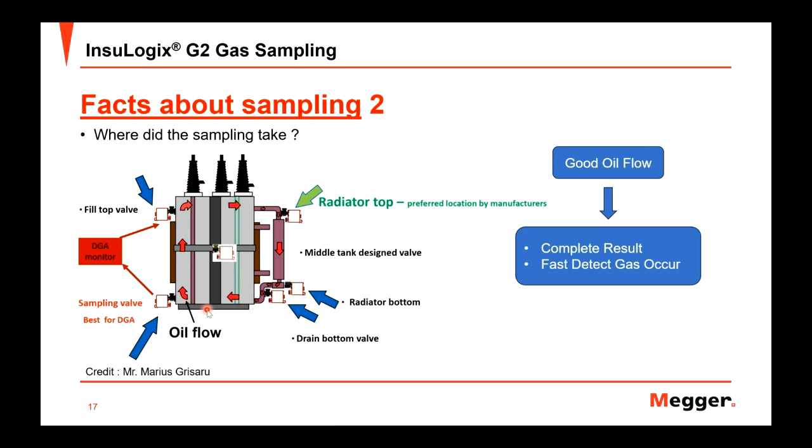But you also have to be careful about the water inside your transformer. If you have a lot of water at the bottom of the transformer, that water is not involved with the insulation at all, because that water is just sitting there. It's not involved. So you have to flush it out until you don't see any water, and then you take the real sample. So you also have to be careful about that.